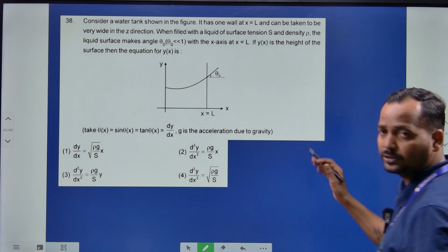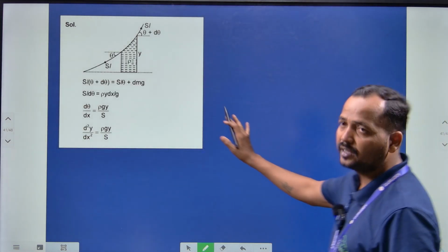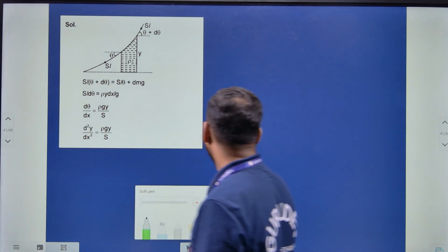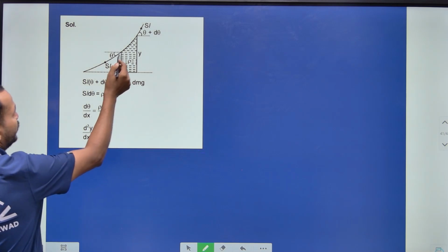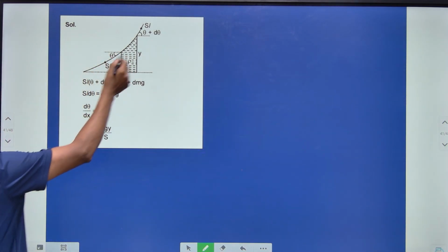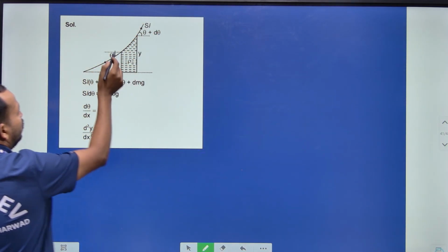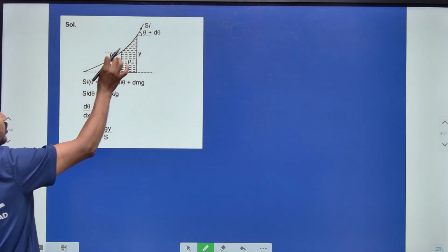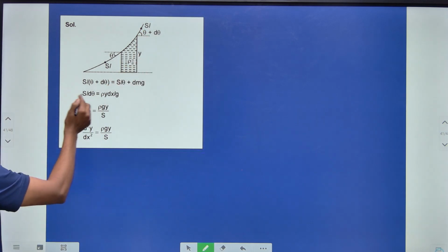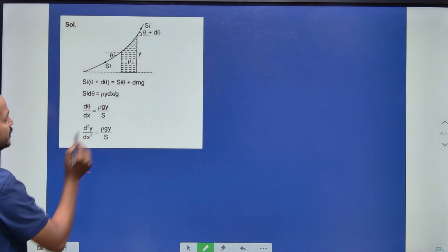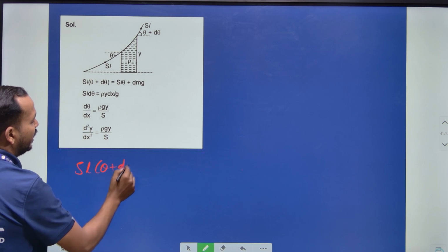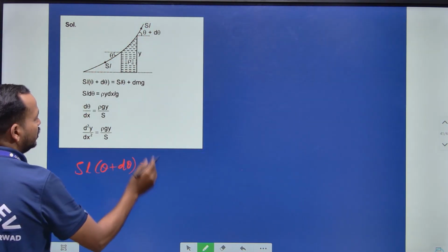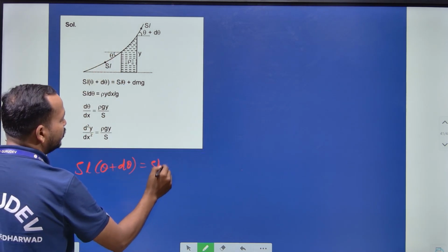तो यहाँ पे इसको सॉल्व करने के लिए ऐसे सॉल्यूशन कर सकते हैं हम। तो इस सरफेस के ऊपर सरफेस टेंशन जो होगा वहां पे नीचे पे होगा, और यहाँ पे जो सरफेस टेंशन होगा ऊपर होगा, और यहाँ जो एंगल है वो थीटा है, और यहाँ जो एंगल आएगा थीटा प्लस डी थीटा, क्योंकि यहाँ एंगल स्मॉलर होता है और यहाँ पे बड़ा होता है। तो यहाँ पे उन्होंने जो इक्वेशन लिखा है सरफेस टेंशन S L (थीटा प्लस डी थीटा), जो यहाँ पे टेंशन हो रहा है विच मस्ट बी इक्वल टू, यहाँ पे जो टेंशन आ रहा है वो क्या है, S L इंटू (थीटा प्लस